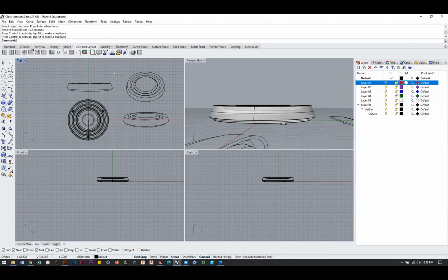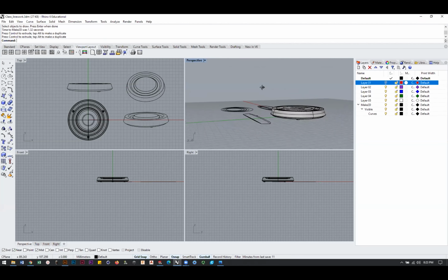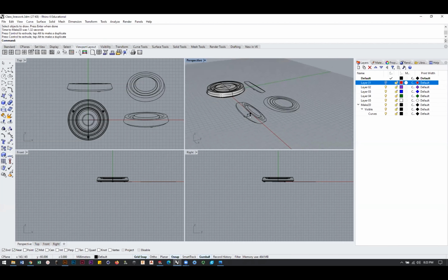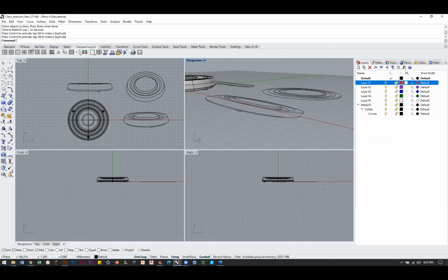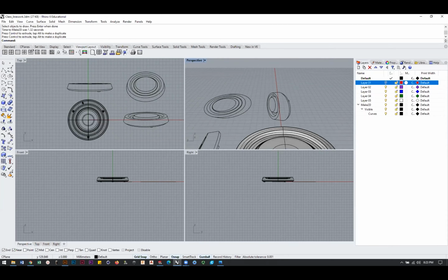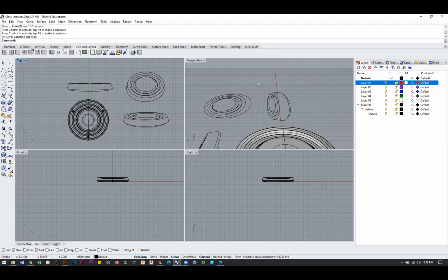As far as presentations and stuff for new designs, this is a really unique thing, and SolidWorks cannot do this. So that's why I would say that it's something that you guys should all definitely know about. If we look at the results in the perspective view, you can see how these sketches end up. They all get flattened down onto that ground plane, and they're also kind of warped in perspective. They look sort of funny. So it's definitely important to understand that the thing you're trying to get out of this tool is always going to be on the top plane.